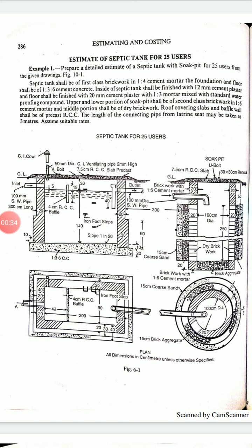Generally it separates the liquids and solids and provides digestion of some organics and storage, mainly by bacteria which live without oxygen, and it also discharges partially filtered and clarified effluent to the drain field for final treatment. And what is meant by a soak pit here?